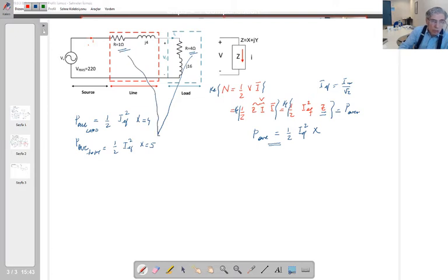Why is it total? That is the total impedance, isn't it? The total impedance real part is this. My load impedance real part is this. The division of those two is going to give me the efficiency. Since these currents are equal, because all these elements are connected in series, the maximum value of the current is going to be the same. So this efficiency is 4 over 5, that is 80%.